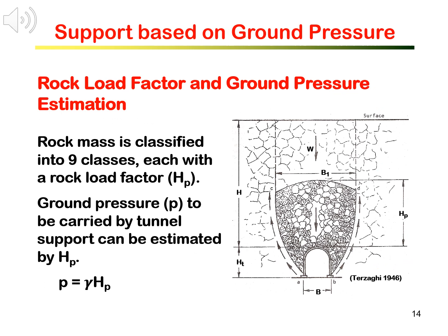Now I want to move to the second ground pressure based support design approach, by estimating the ultimate ground pressure that needs to be supported and designing the support as a load-carrying structure. As we mentioned, we can obtain the desired ground pressure using rock load factor. Rock load factor is perhaps the first rock mass quality classification system. It is indeed a rock mass behavior classification system meant for rock support design.